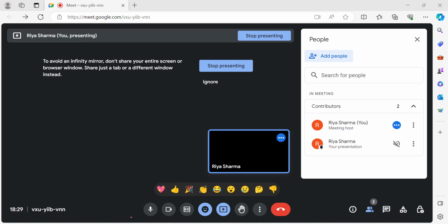A 0.5 meter cube cylinder contains nitrogen gas. Try to write every part. 600 kilopascal. What has been given? 300 Kelvin temperature, isothermally. So isothermally means that compression happens. So will the work done on the gas be positive or negative? Think about the signs also. And what is the formula given? Then think about the ideal gas law, and then your answer will be there.